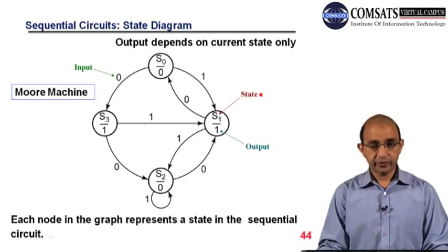You can see that we have the state diagram mentioning different states. So here, if I tag, this is the state S1, and this is the state S0, and this is the output. In the denominator we have the output, in the numerator we have the state. And this transition is shown by this arrow. So here the cause of this transition is this input. So we have to apply 0 if we want to move from this state to this state.